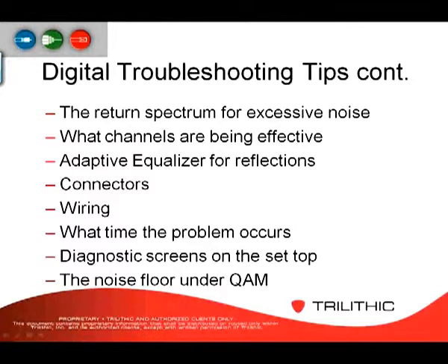Use the diagnostic screens on your set top. That's a useful troubleshooting tool, but what you see on the set top and on your meter should agree with each other. But if, let's say, you're looking at the plant coming in and everything is nice and clean, but the set top box itself is showing errors, it could be a problem with the box. And then look at any noise that's falling under the QAM carrier. Using the QAM EVS will point you to a lot of problems that you wouldn't typically see.